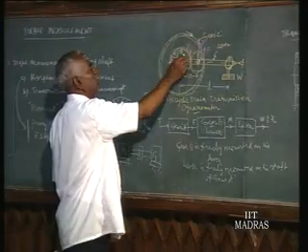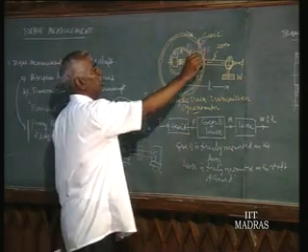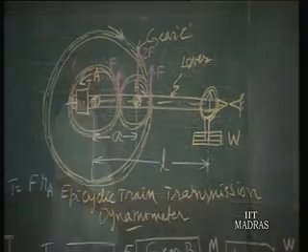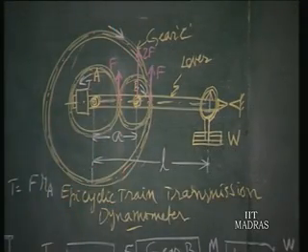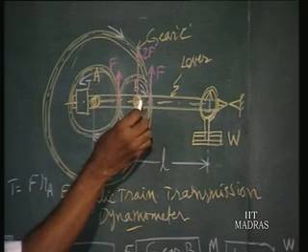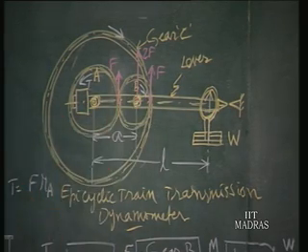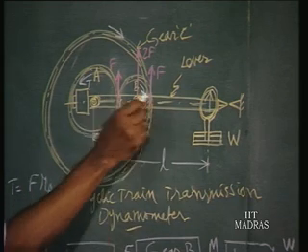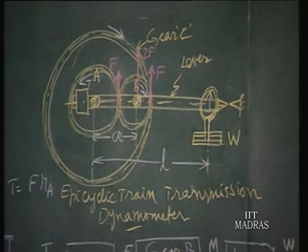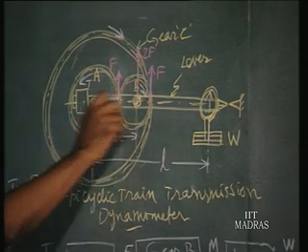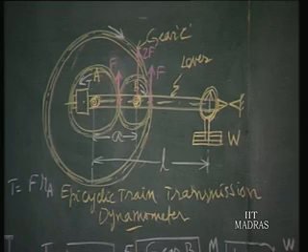Now when the gear A rotates, B will rotate in this direction, and B is driving the load on the gear C. So the reaction of the load will be in this direction. Gear C is rotating in this direction, so the reaction of C will be in the opposite direction. So you will find 2F there, and the reaction of these two forces will be taken up at the center support of the gear B, so here you have 2F as the force on the lever, since B is freely supported on the lever.